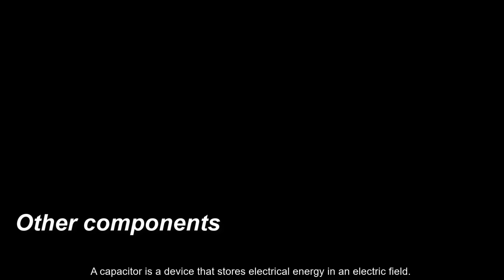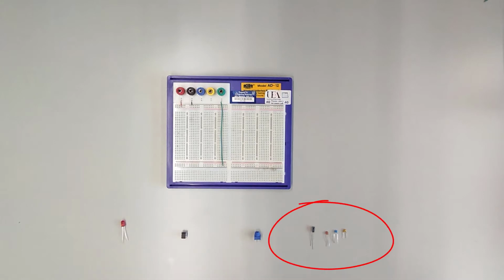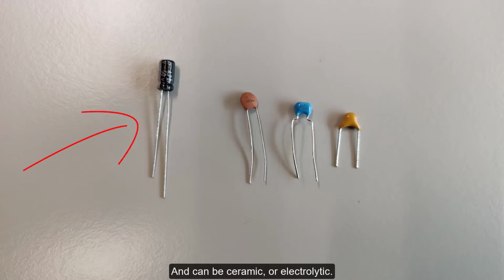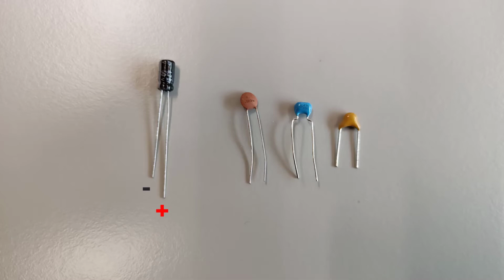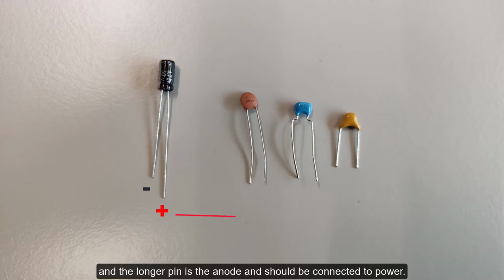A capacitor is a device that stores electrical energy in an electric field. Capacitors come in different shapes and sizes, and can be ceramic or electrolytic. The electrolytic capacitors are polarized. Remember, the short leg is the cathode and you need to connect it to ground, and the longer pin is the anode and should be connected to power.